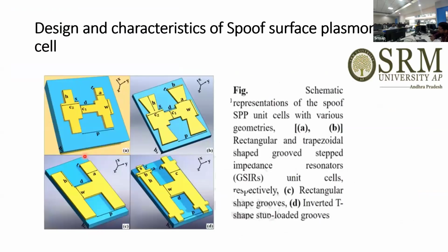You have to design the unit cell first, and these dimensions have to lie within the asymptotic frequency limit. These are the different types of unit cells existing in the literature, designed in the millimeter, micrometer, and nanometer range, below that frequency limit. If you change any unit cell, then the entire waveguide structure will change.